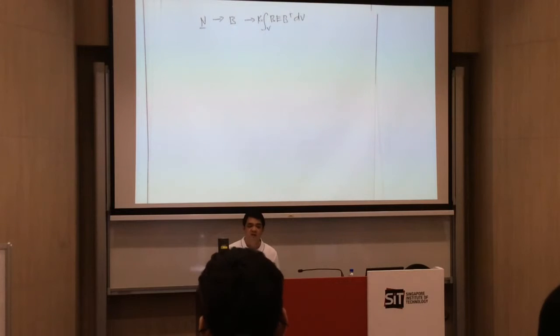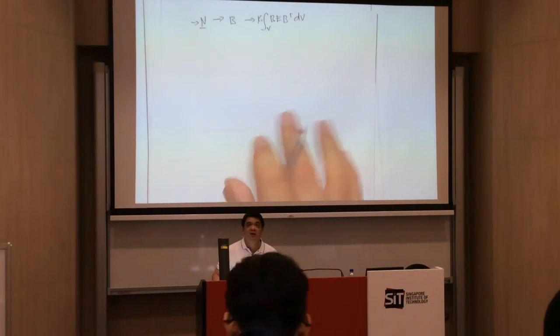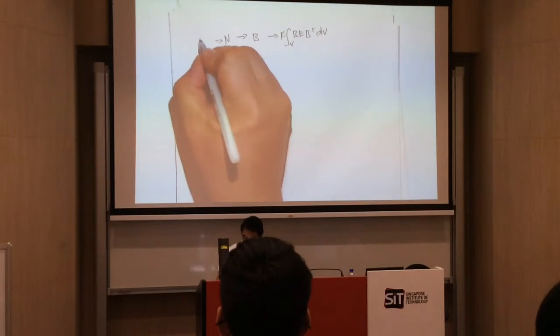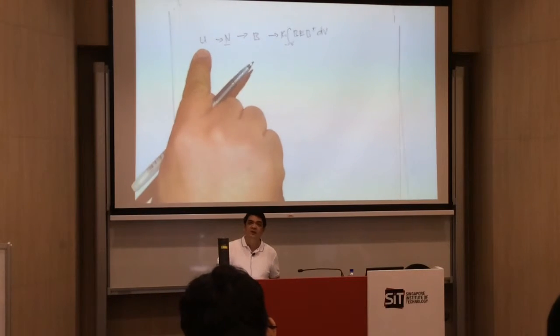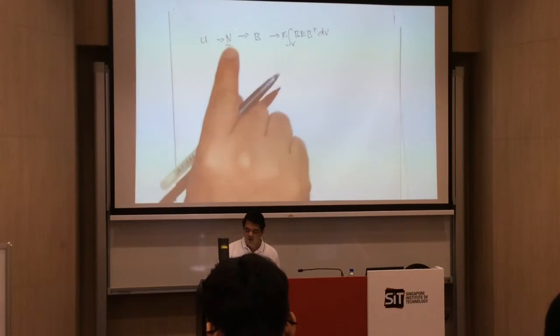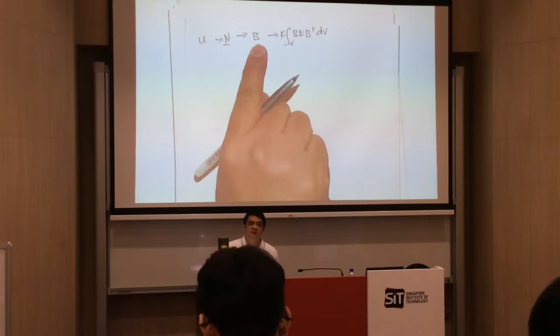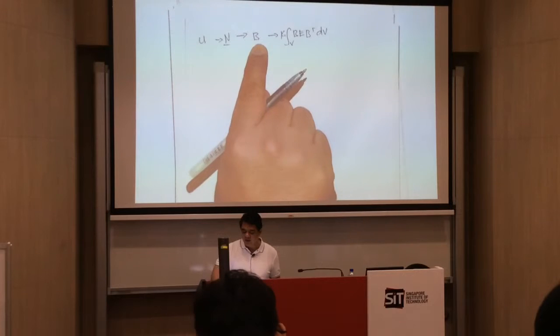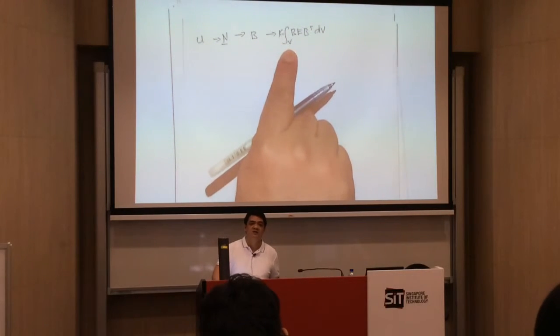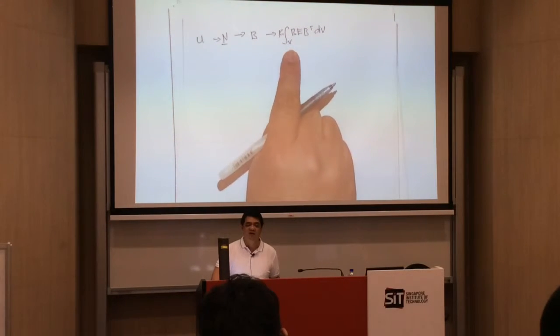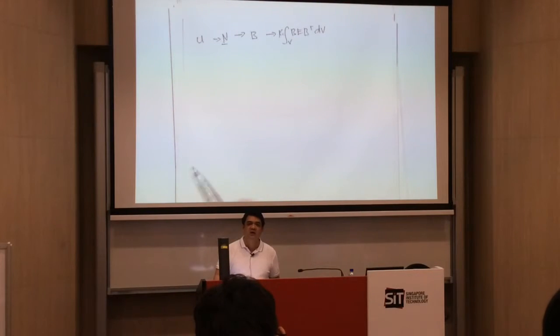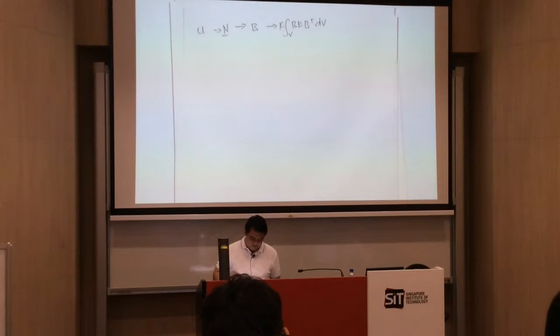Once you get this one, depending on your assumption, so again, if you want to start, you come up with your displacement function, solve your shape function, determine your strain displacement matrix, determine your stiffness matrix. So once you have that, then it will be straightforward now to calculate for your F equal to K multiplied by U. So let's have a look.